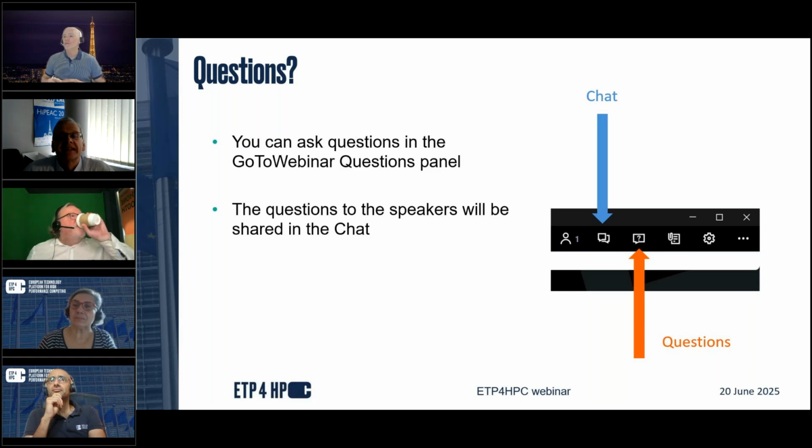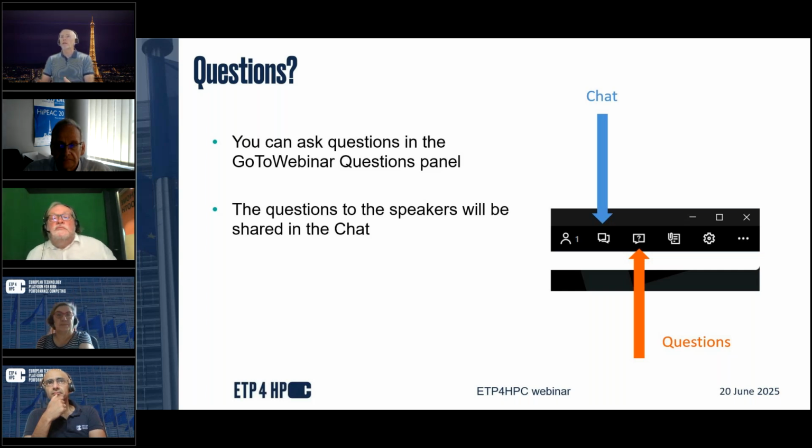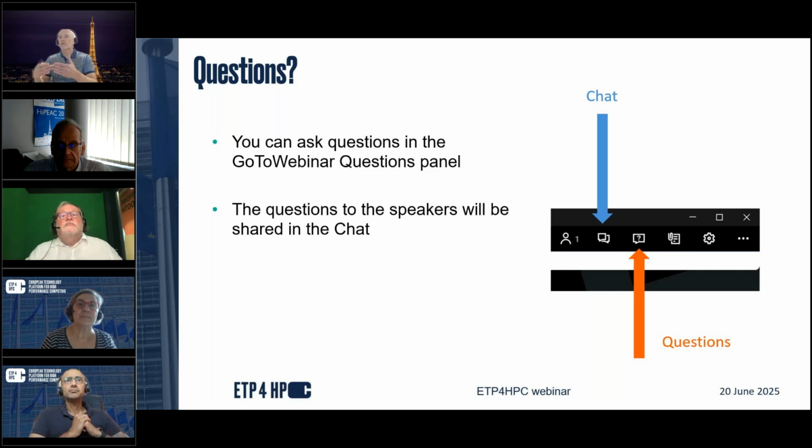Yeah. So people talk about this chiplet marketplace, and they talk about putting Lego blocks together, and this is multiple levels. The first would be, what are the interconnects? Is it standardized? How do they connect together? Today, if you build two chips blind on UCI interconnects, and let's say you agree on UCI standard as opposed to advanced, you already know that they won't work together. There's just too much gray in the spec. So you already have to be working cooperatively today to make sure your chiplets will interconnect.